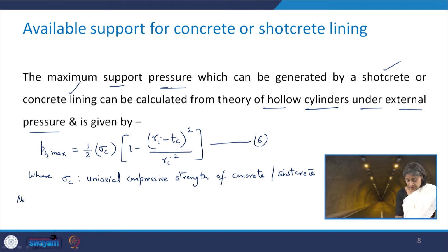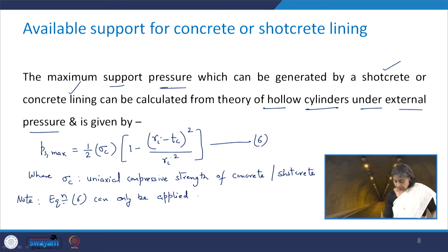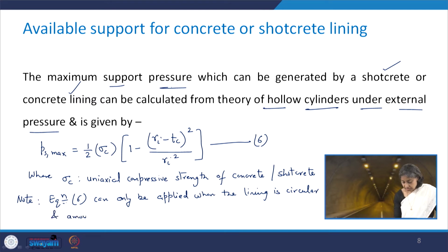So here we need to take a note that equation 6 can only be applied when the lining is circular and the amount of overbreak is limited.